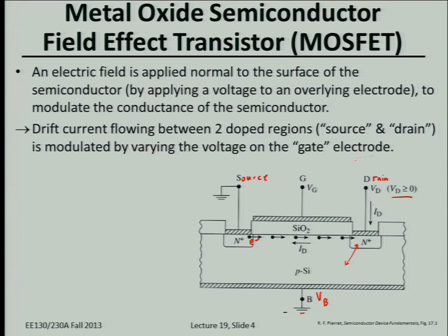that all of the voltages in your circuit are anywhere from 0 volts, which is ground, to the supply voltage, VDD, which is on the order of about 1 volt. Okay, so assuming that any of these terminals in your circuit could be biased anywhere from ground to the supply voltage VDD, basically this means that you would like to bias the body so that no matter if this N+ region is biased at ground or at VDD, there's not going to be significant junction leakage or junction current flowing.